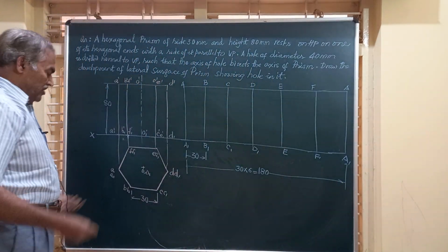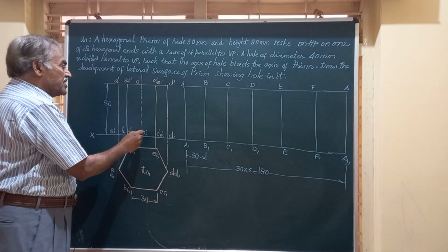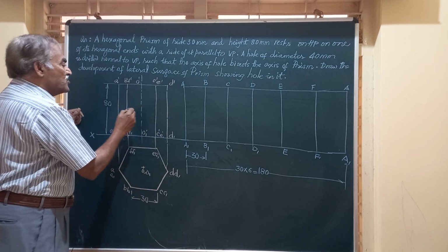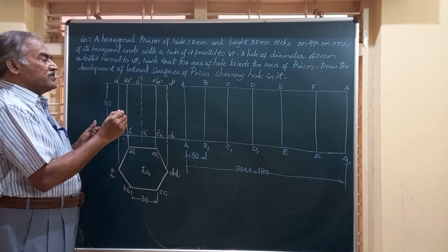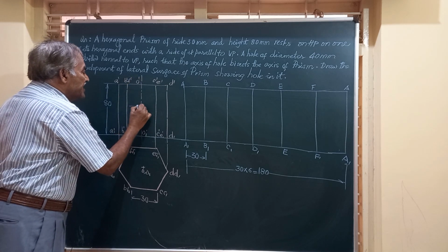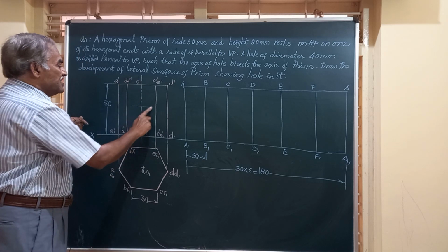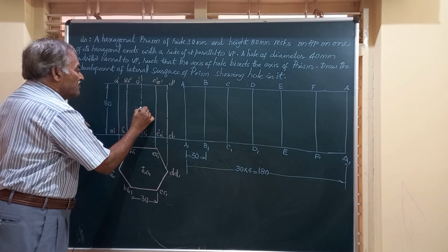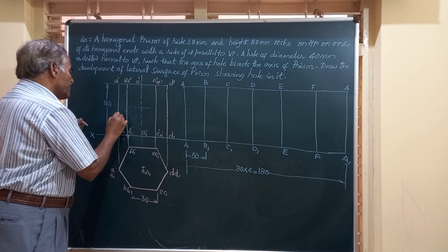Friends, now a hole is drilled at the mid height O dash, O1 dash on this face. So the axis of the hole, which is drilled perpendicular to VP, bisects the axis of this. So I am going to take the midpoint of this height, that is totally 80. I will mark a point at a distance of 40 millimeter from the base. So this is 40.